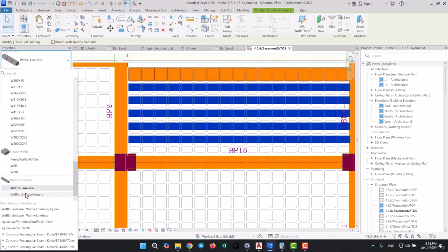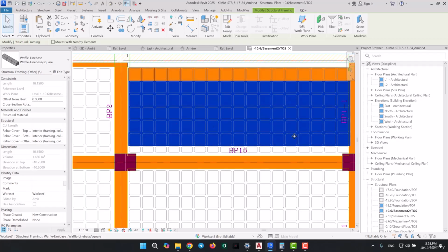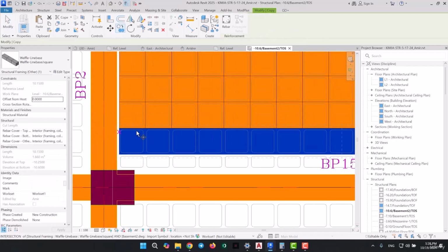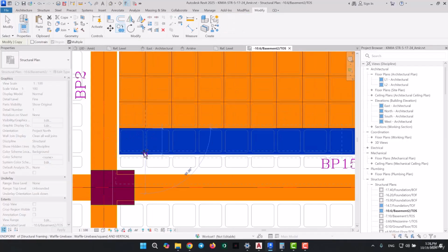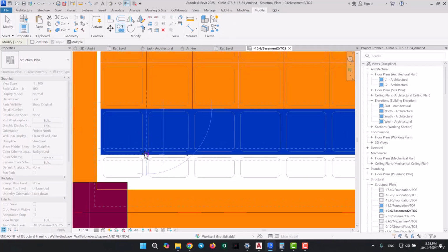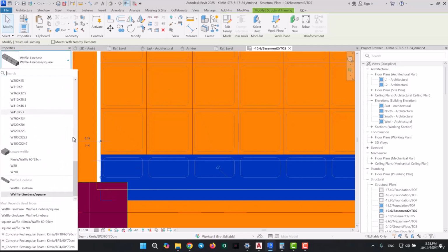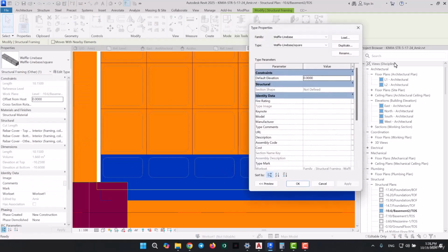We're going to change their type to the square. And as for this final row we're going to be drawing, we're going to set that to the rectangle type. So do you see how it goes? Now you no longer need to switch between your families back and forth, but instead we've associated a parameter to one single family to make two types of it, so we can easily switch between the shapes.